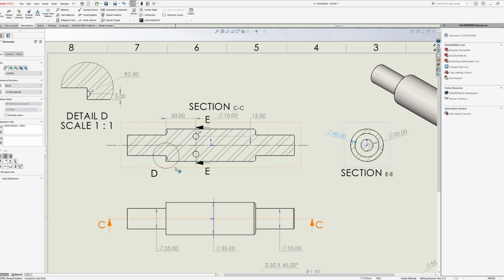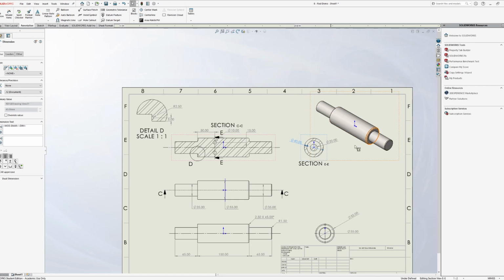And we could, if we wanted to, possibly do something identical for these guys as well. Just to make sure that, because from this angle, we can't even see that we have that cutout there. So perhaps how you orient your parts is also helpful as well. If I had flipped this 180 degrees, then doing much to dimension this cutout here, other than showing the distance from the edge and the radius of it, that would be plenty. As it stands right now, since I'm not looking at the left view of it, it's kind of harder to tell that that's actually going on there.